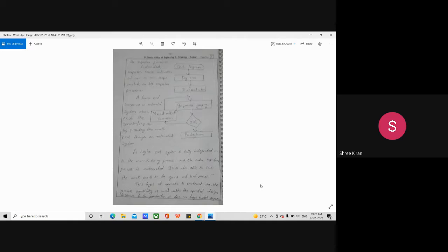In the case of automatic inspection, we will have a CNC program. We first check the CNC program to see whether it is well placed and that no corrective actions, updates, or errors are present while running it. Second, we do a dry run to check that the whole process is exact and there are no issues. Then we have a trial production, which means manufacturing a prototype of the product to check all the dimensions and aspects against our measurement requirements and see that it serves the purpose well.